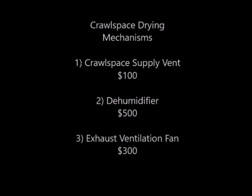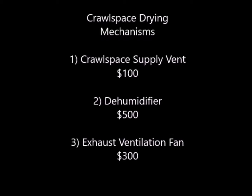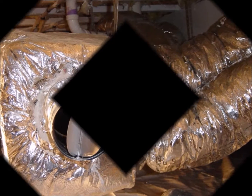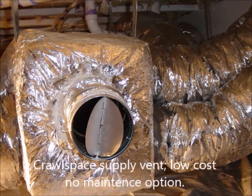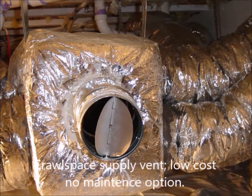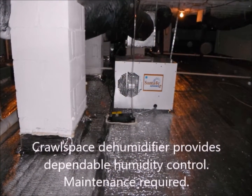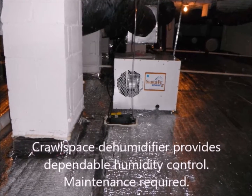Crawl space drying mechanisms consist of three: the crawl space supply vent, a dehumidifier, or an exhaust ventilation fan. Crawl space supply vents are a low cost and no maintenance option. Crawl space dehumidifiers provide dependable humidity control, yet require maintenance.